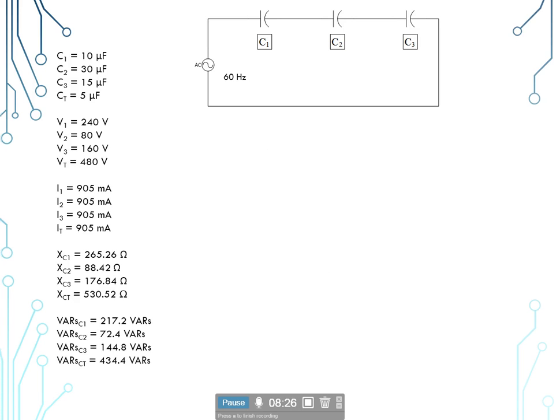Here it all is listed out after we've made the calculations. Again, you would use these calculations that we calculated. You would now go out to the circuit, make your live readings with your meters, and come back and compare them to these. Are we in the ballpark? Then you don't have an issue with that part of the circuit. Is it way over foul ball, over left field? Then we have an issue with that part of the circuit. We need to look a little closer.